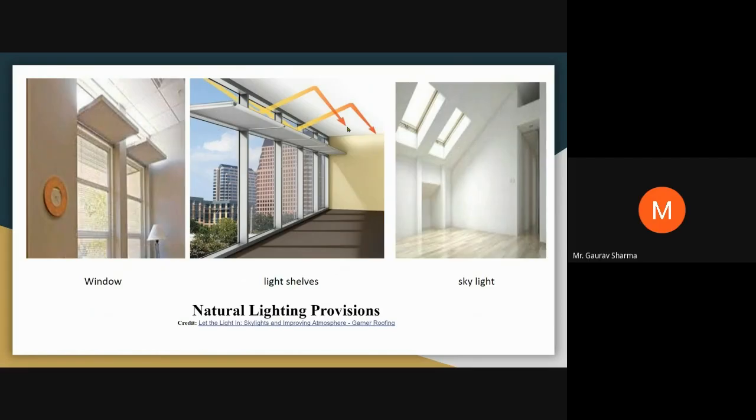See, you can compare it with the relevant images. Suppose you are introducing lighting inside the building with the help of this kind of skylight windows over there. In that case, what will happen? The low elevation altitude sun will enter into the building directly. Yes or no? Or even the higher altitude sun will enter directly. At this position, the higher and lower altitude sun both will enter into the building directly. Agreeing or not?